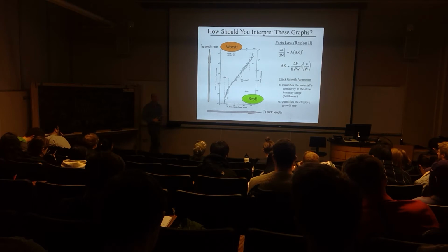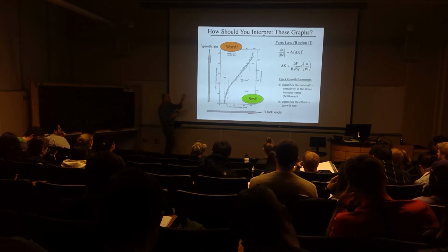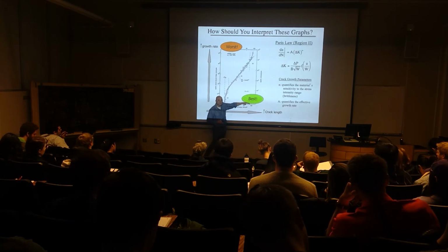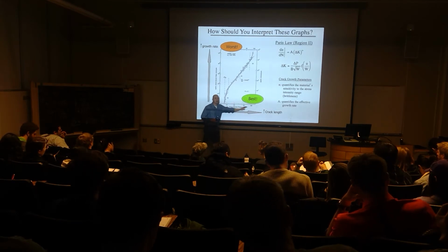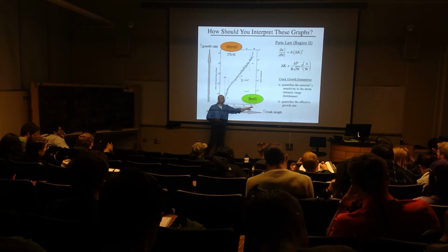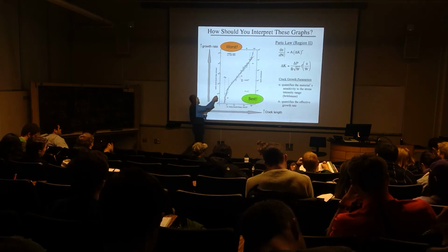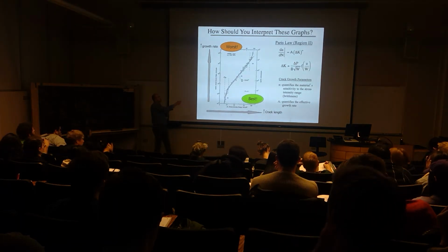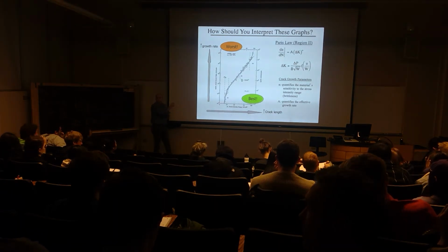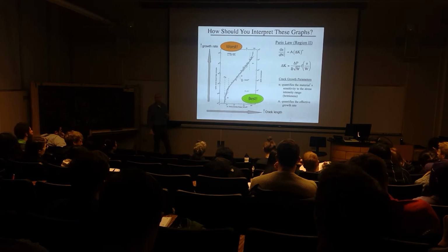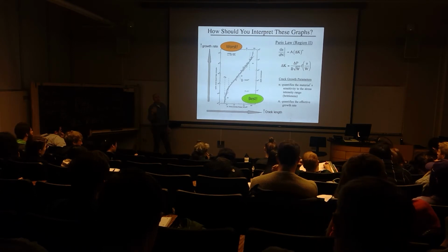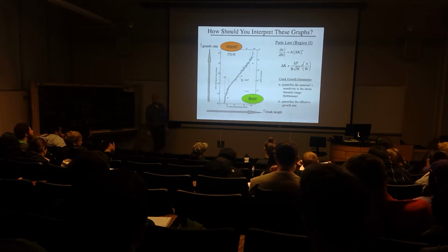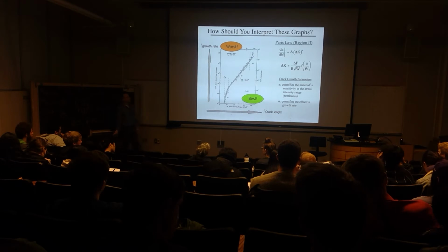If I compare two different curves and look at their positions on this diagram, the best materials are down here: low slopes and low growth rates despite the fact that they have large stress intensity ranges. If I'm up here, it means the material is not quite as good, because it has fast growth rates for low stress intensity ranges. So you always want to think about that when you look at materials from a design perspective, but also when you compare them for what happens due to the environment.